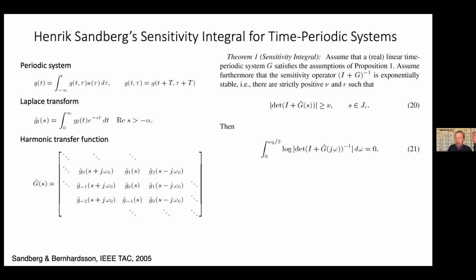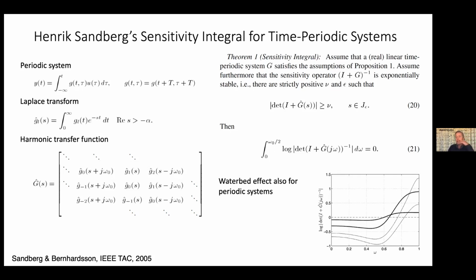But basically, otherwise, the interpretation of this sensitivity integral for periodic system is very similar as before. So for instance, we have now the waterbed effect that we can express through this sensitivity operator instead. Just as you saw previously, if we push it down at some frequency, it needs to pop up at other frequency there.